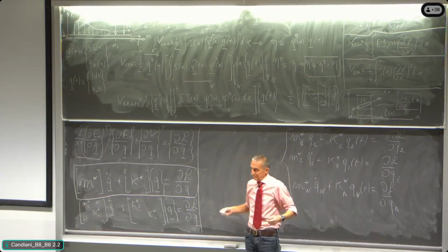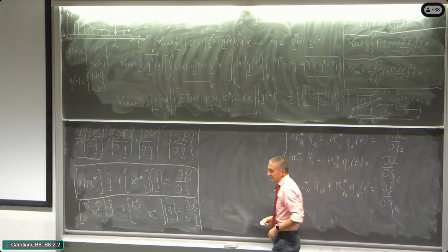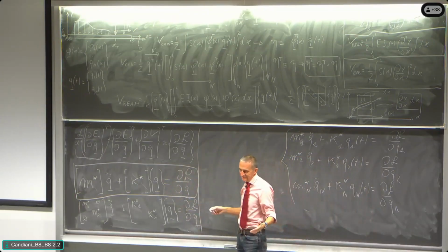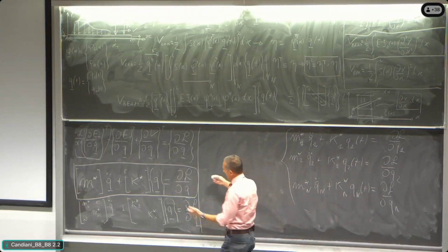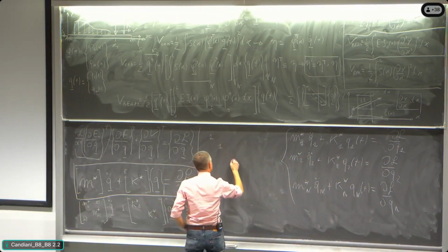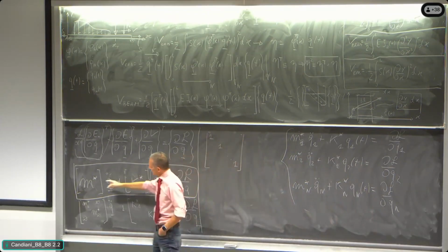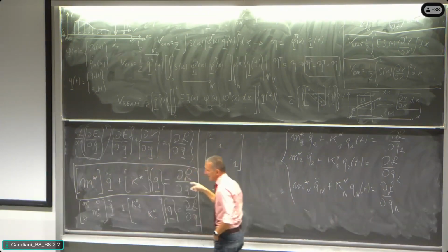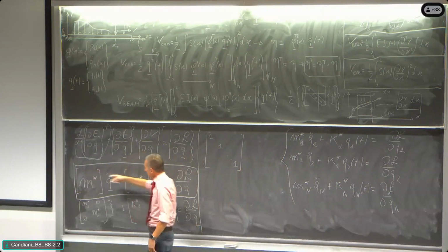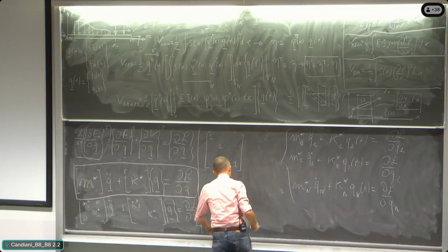But you could make the exercise of identifying the modal shapes experimentally, identify the frequencies, and the left side of the problem of the modal approach is written without doing anything, because you write that the left side of the problem is 1, 1, 1, because we are dividing by m star i each row. We are dividing by m star 1 the first row. And so we find over here omega 0 squared. And so you write this, all right.